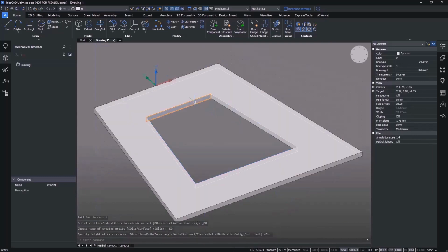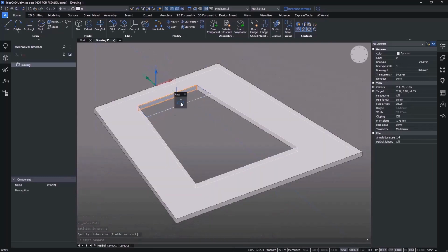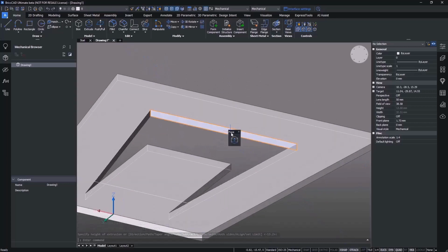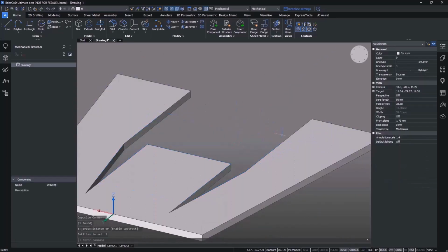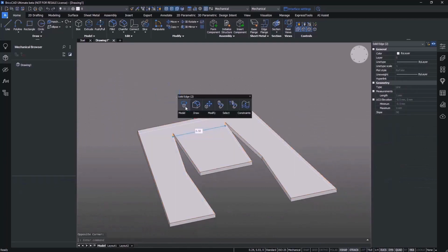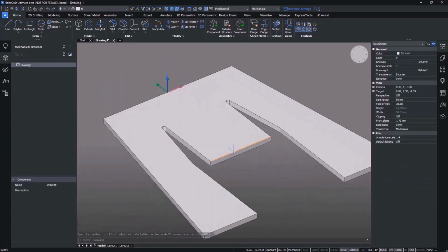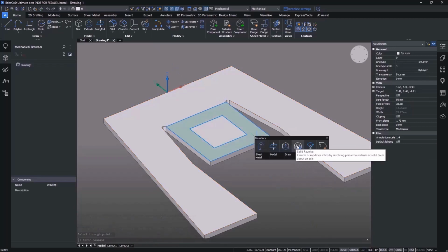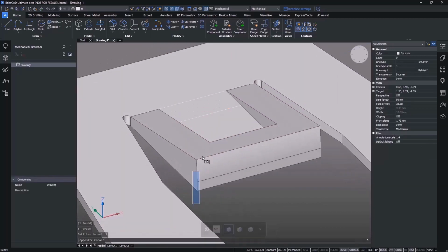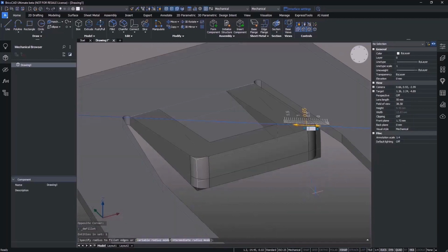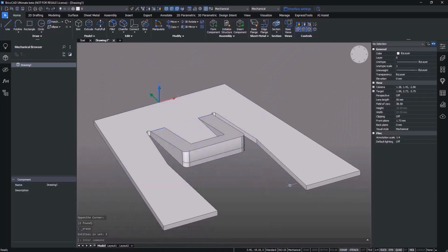Click on the modeling task, such as extrude or draft or extract, and then drag the design into the desired configuration. Direct modeling eliminates the need for the history tree commonly used by other 3D modelers. There's no need for a history. Just select what needs to be edited or created and model it directly.